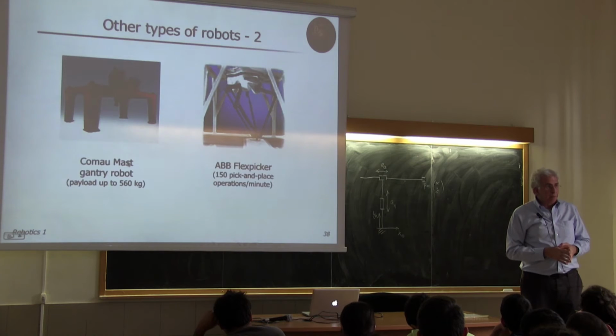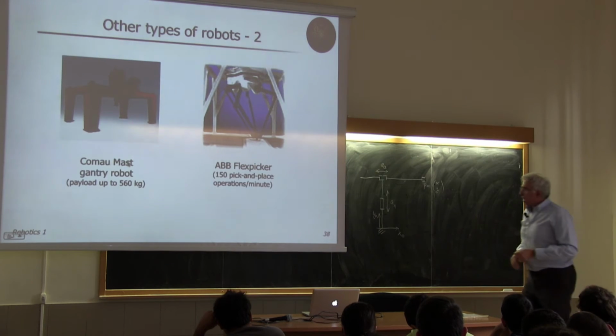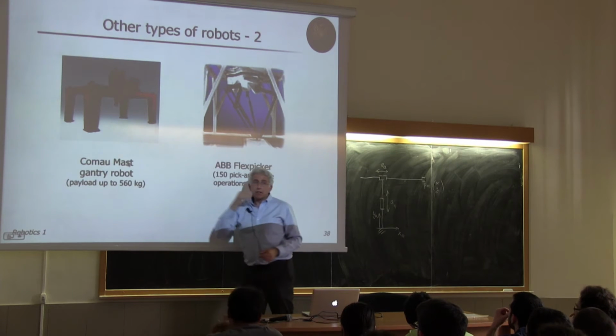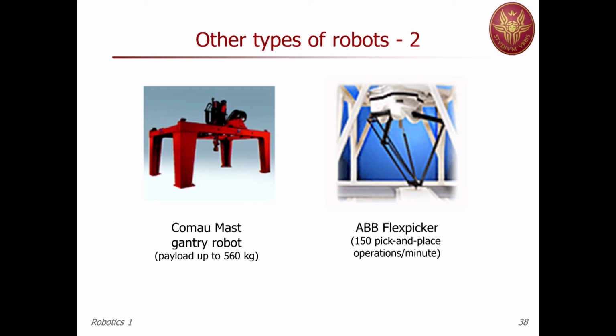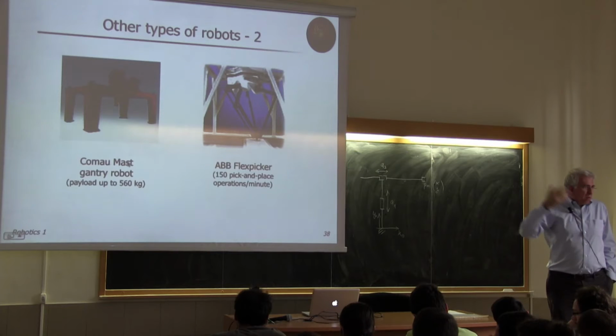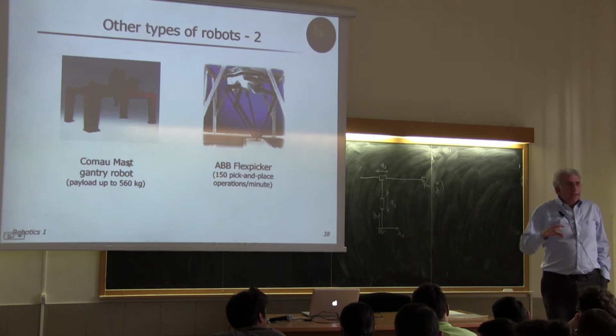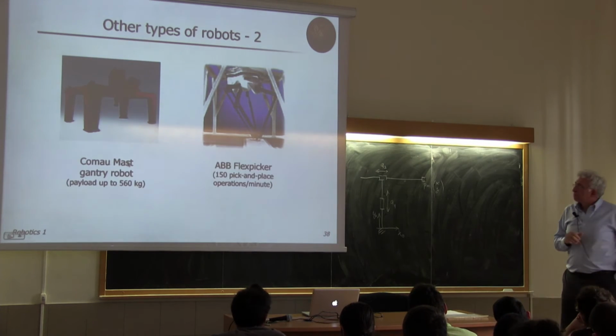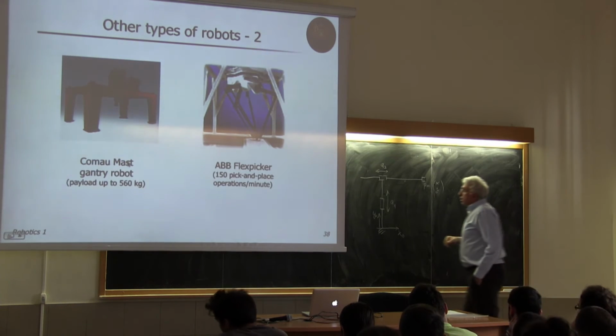You may have a completely different mobility if you change the order of the joints besides their type. Okay? So this is the gantry robot, another class of serial manipulator where the first 3 or 2 joints are prismatic, depending if this moves in 3D or only in 2D. And typically, although not exclusively, the last 3 joints are revolute and provide a spherical wrist. Here is another